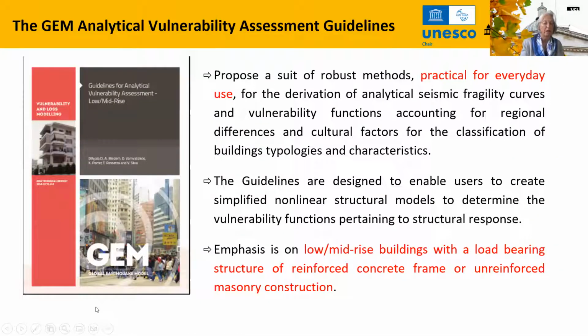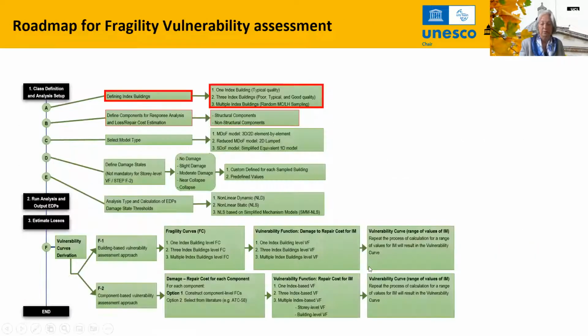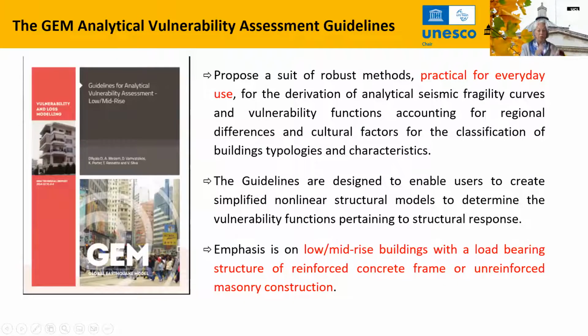How will we provide that? By referring to the GEM analytical vulnerability assessment guidelines. This proposes a suite of robust methods, practical for everyday use, for the derivation of analytical seismic fragility curves and vulnerability functions, accounting for regional differences and cultural factors for the classification of building typologies and characteristics.